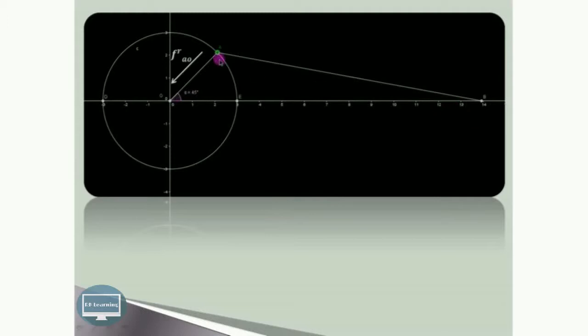Now in this particular case neither A is fixed nor B is fixed. So we consider the radial acceleration of either B with respect to A or A with respect to B. If we consider A as the center, then the radial acceleration of this connecting rod will be directed towards the center, that is A. So this is the radial acceleration FRBA which is directed towards A. Tangential acceleration is always perpendicular to the link. So here this is FTBA which is perpendicular to this link, which is nothing but the connecting rod.